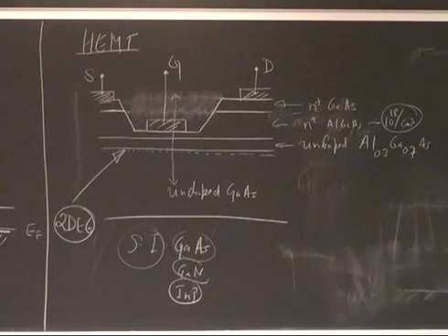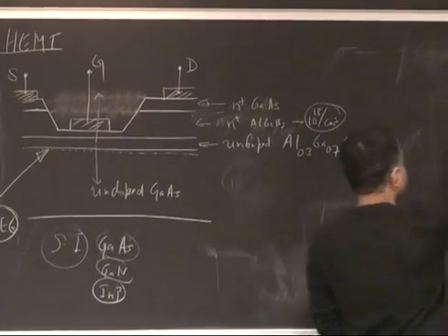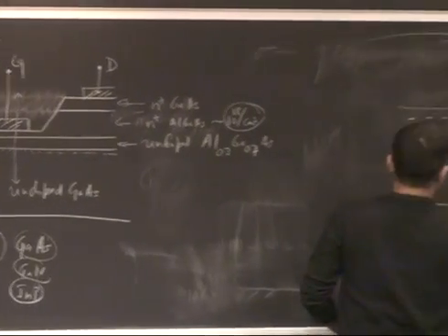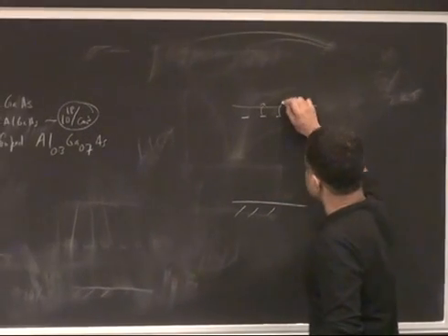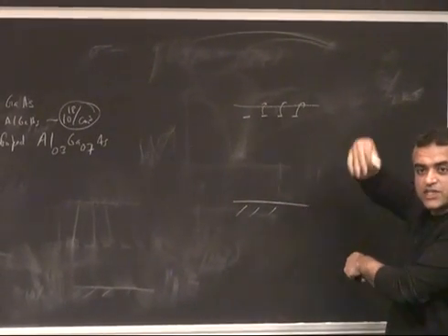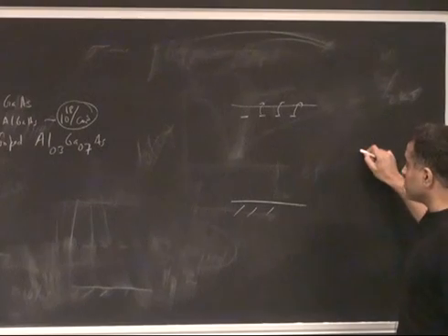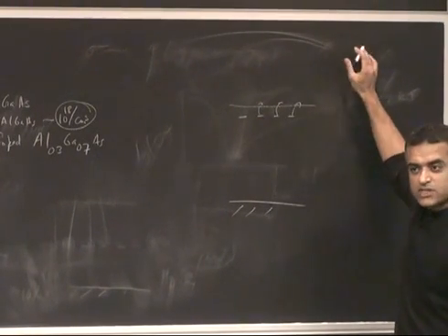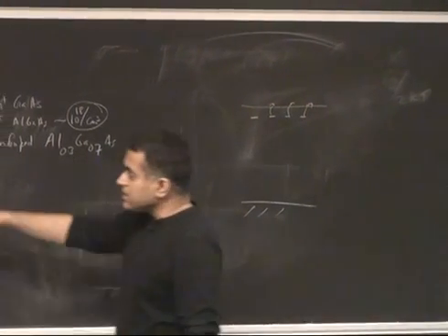These electrons, we'll see, are there because of charge transfer. This is a 2D electron gas. It's kind of like that. And these electrons are sitting above the Fermi level, above the conduction band edge here. If you take an N-type doped gallium arsenide, you have electrons in the conduction band because of thermal activation. Heat kicks them out. But if you take it down to very low temperature, you lose all those carriers. They exponentially decay and fall back. Here, you can take it to any low temperature.